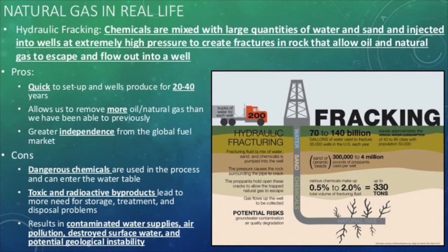The biggest news with natural gas at the moment is hydraulic fracking, or just fracking for short. Fracking is a process to remove natural gas by mixing chemicals with water and pumping it into a well under high pressures to fracture rock in order to release the gas. It is quick to set up and lasts for decades, allows us to remove reserves of natural gas that were previously economically unattainable, and lowers our dependence on global energy sources.